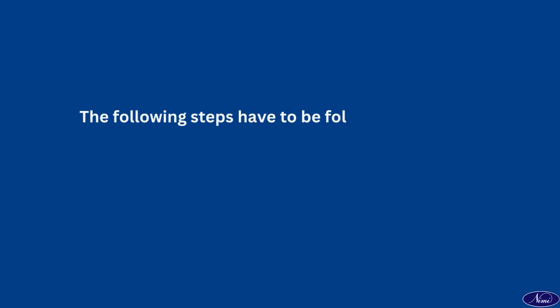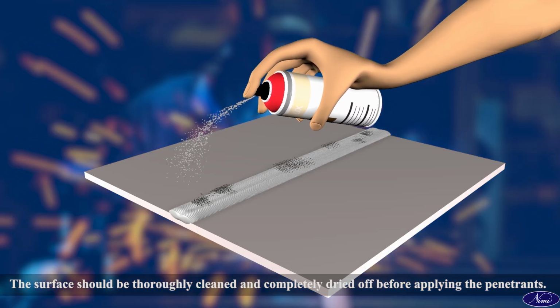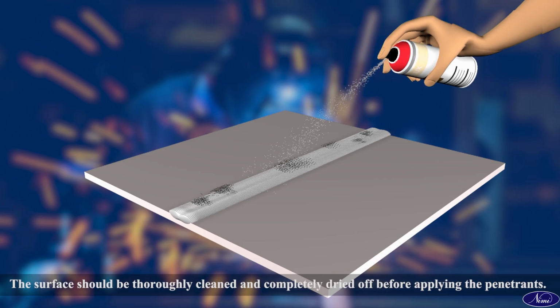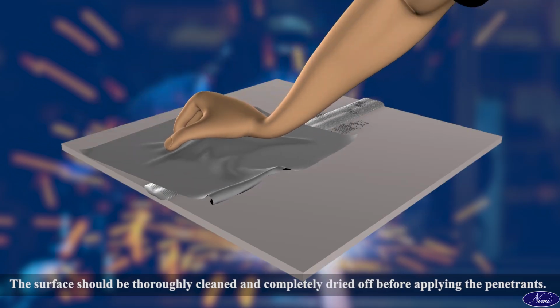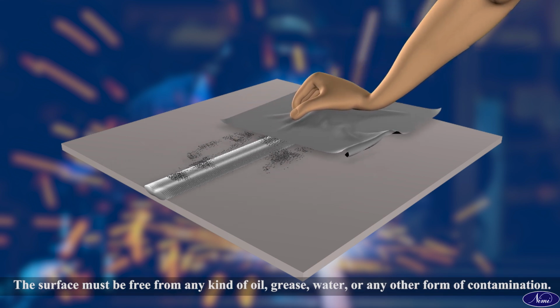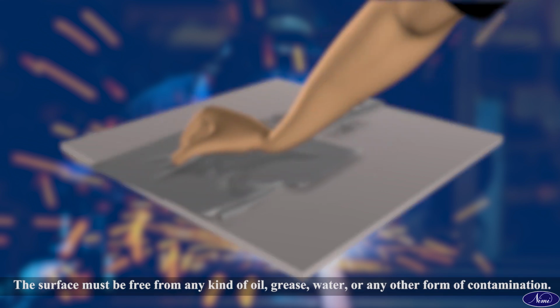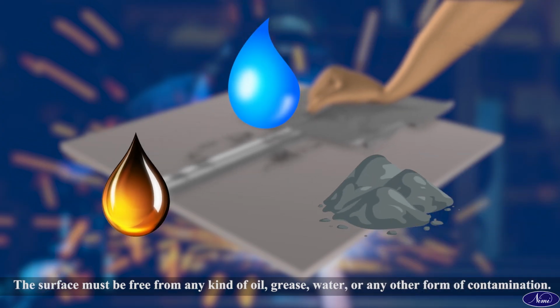The following steps have to be followed during the liquid penetrant inspection. The surface should be thoroughly cleaned and completely dried off before applying the penetrants. The surface must be free from any kind of oil, grease, water, or any other form of contamination.